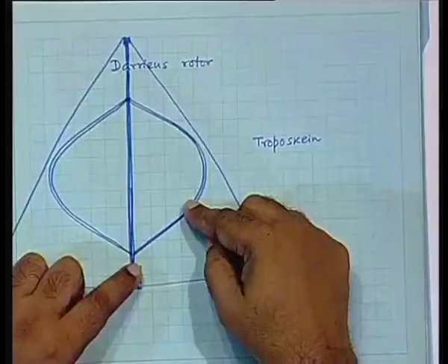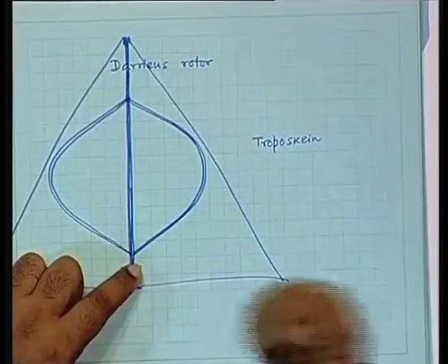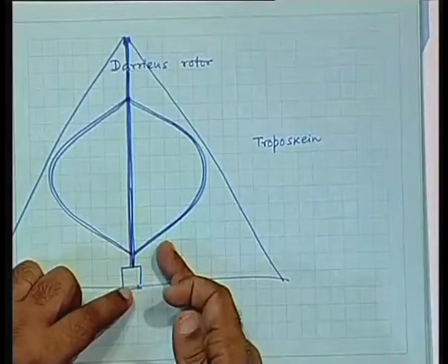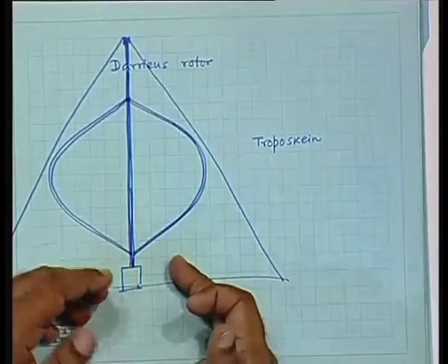Which means that as it rotates, the only stress that can be produced in these blades would be just a tensile stress. Do you understand? There cannot be any bending stress, because if it were flexible and rotated, it would take the same shape. If you make it in that shape, then the only force produced is the tensile stress that stretches.